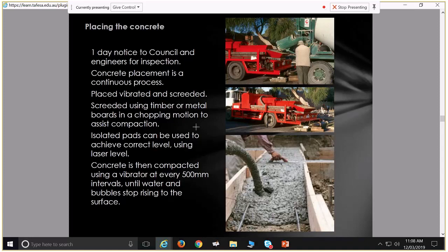That is a real issue. So your strength in concrete comes primarily from your cement-water ratio. If you've got weak aggregate, whatever's the weakest link is going to fail. If the stones in your concrete, the coarse aggregate, are really weak, well, that's going to break. So you need really strong aggregate. Then you also need really clean sand to bind well with the cement, because if you've got clay in there, it diminishes the binding. If you've got those things right, if you've got clean sand and strong aggregate, then the strength of your concrete comes from the cement-water ratio.